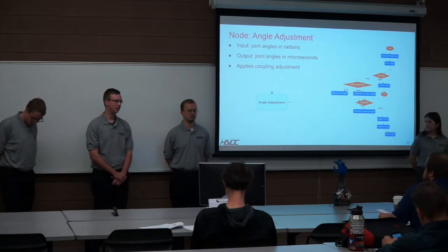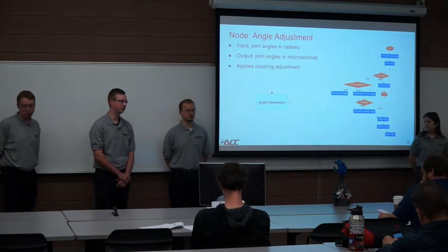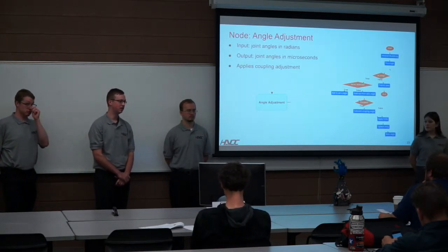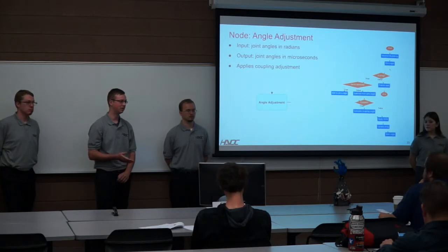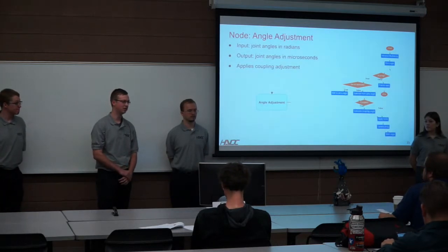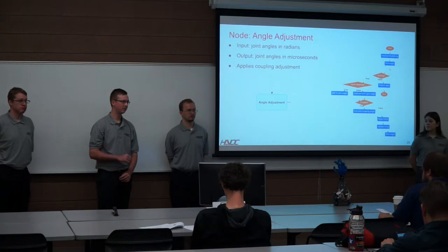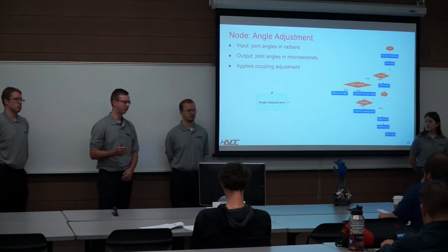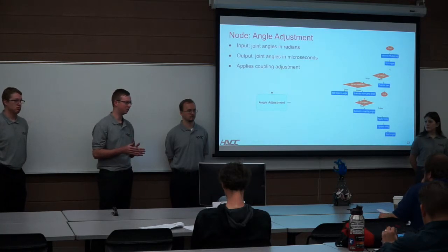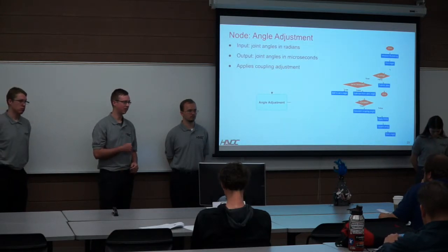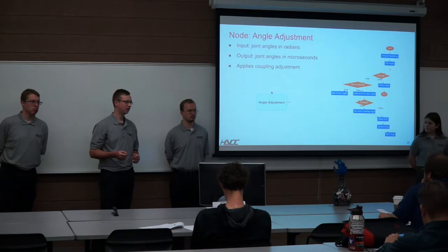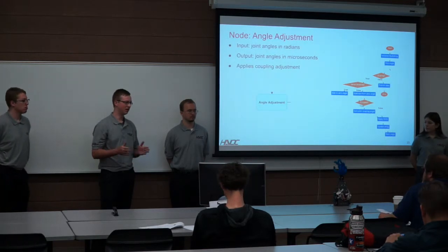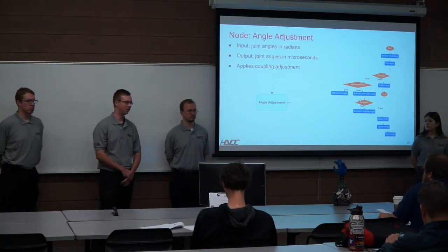Yeah, so we did our analysis in the prelim semester with MATLAB simulations, and we sampled the 960 hertz PhaseSpace data in our simulation, and we chose a buffer of 80 frames from data that we found to get a small enough lag on the system so that we don't have a large delay between the angle updates, and a wide enough buffer so that the noise would be reduced a fair amount.